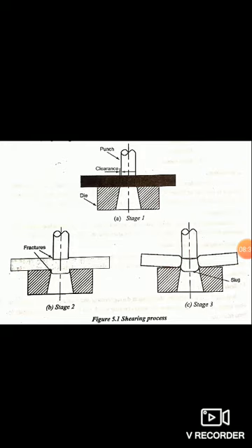At the end of the cutting operation, a small portion of the deformed material is projected out as tensile burrs. We can see it below the workpiece, at the top of the slug and at the bottom of the parent sheet metal.